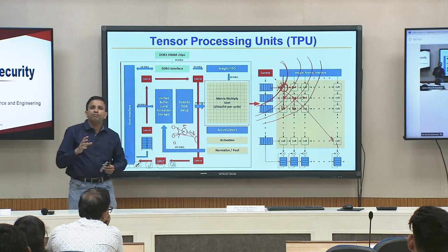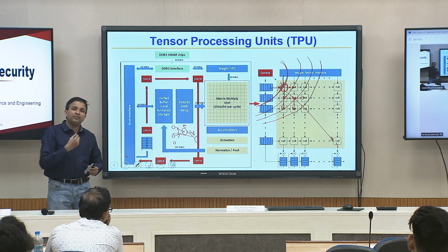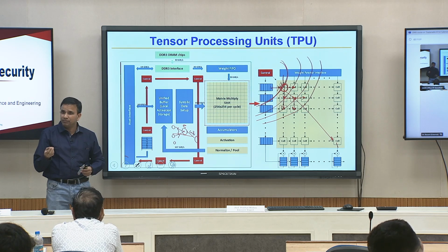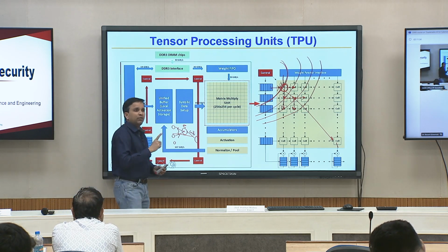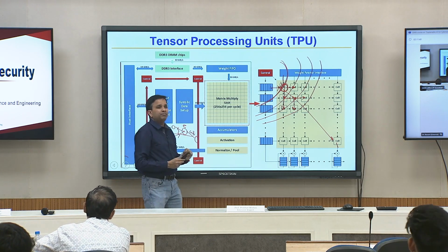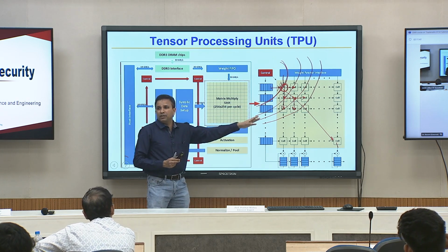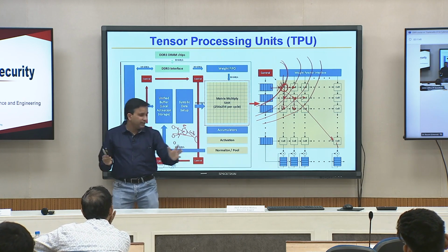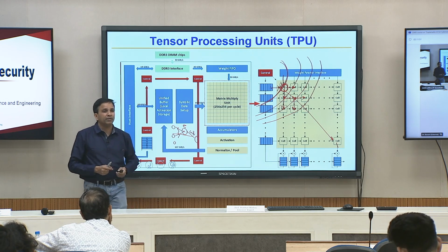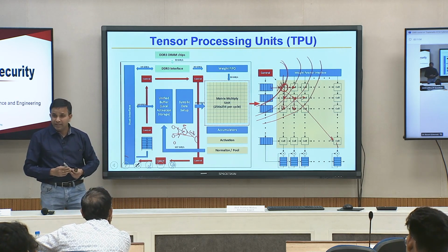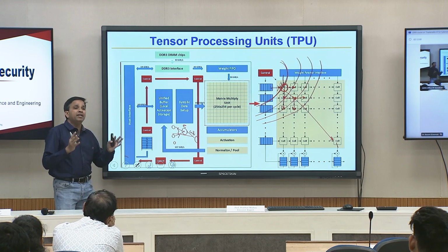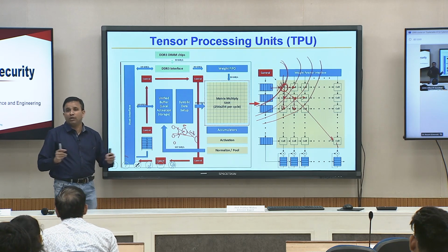Any of you have any confusion about this basic idea? The only thing I tried to highlight is how it is a systolic array architecture, and how it is different from other computations. This is not generic. This is going to accelerate only if your computation or your program has computations like the neural network, only then it is powerful and useful. If you have an AI model or architecture that does not have computation propagation, then it is not going to be helpful. It is not a general purpose acceleration like FPGA. So, this is very customized for accelerating neural network types of AI models.